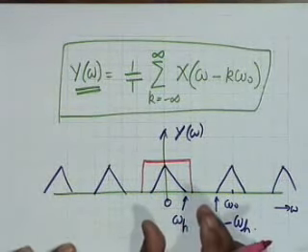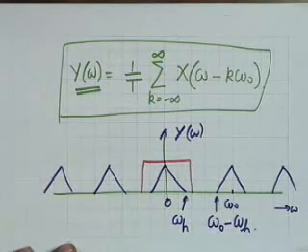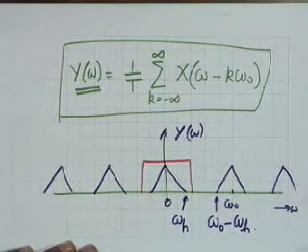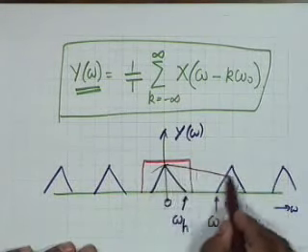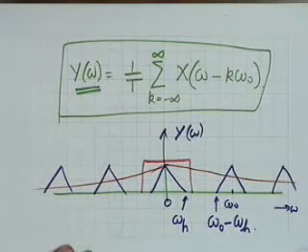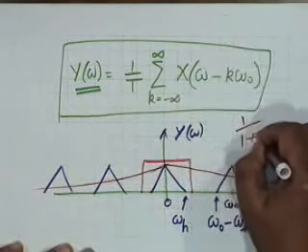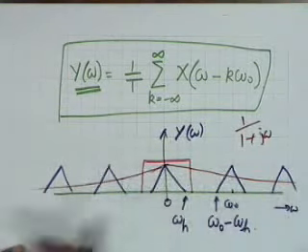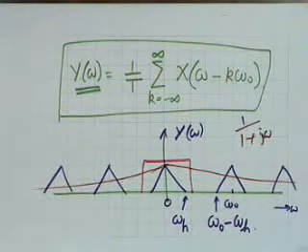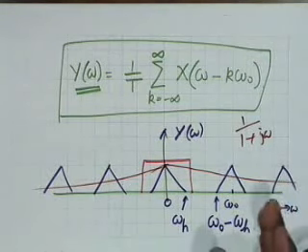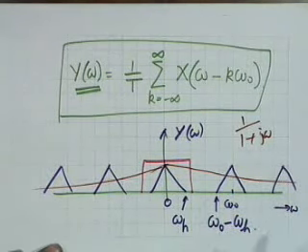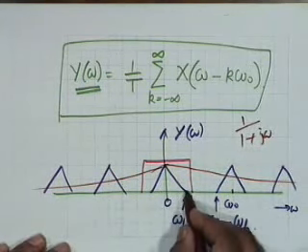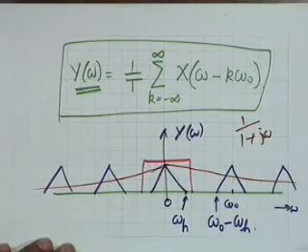So for the recovery of the original signal, this is the discipline, that omega h must be finite. Suppose the signal spectrum was like this, let us take a different color, which is the spectrum of 1 by j omega, then obviously it's not band limited at all. It goes to plus infinity and minus infinity, and I cannot sample it and recover the original signal. That is, a part of this shall not be able to represent the whole. Therefore omega h is one of the constraints. Omega h must be less than infinity.